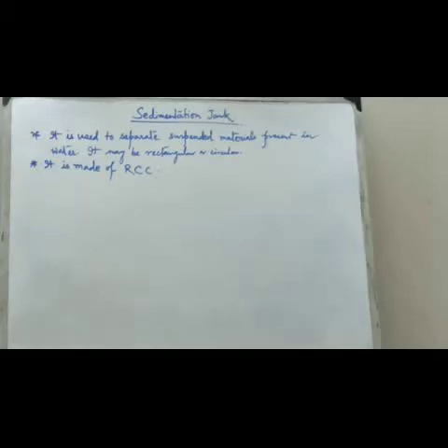Now, rectangular tanks with horizontal flow are generally preferred to circular tanks with horizontal, radial or spiral flow, because this type of sedimentation tank is more efficient and it can remove as much as 70% of the suspended impurities present in the water.